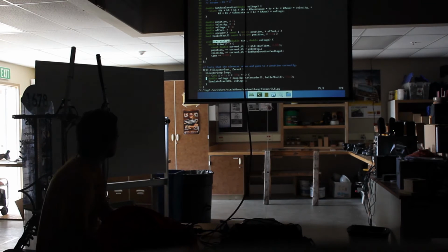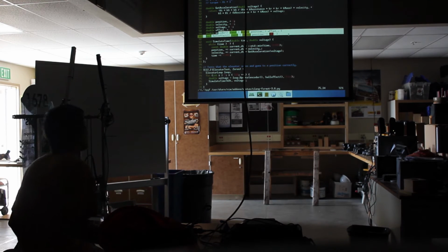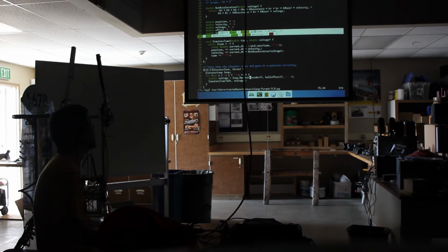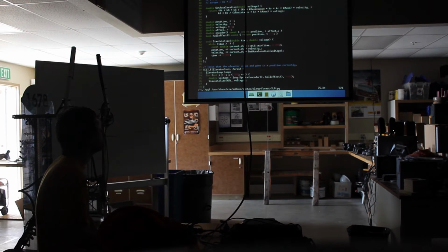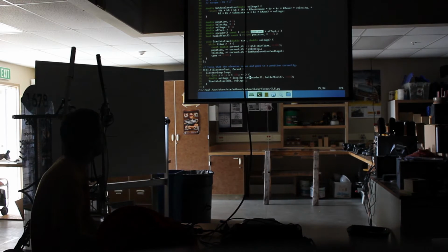So let's walk through a little more what's going on here. In Encoder, we've got written some functions up here. So we've got our encoder value is computed as the absolute position plus some offset. So this is, if you don't start the encoder where it's perfectly at 0, you start it off somewhere. You're going to get a different value for the encoder than your actual position.